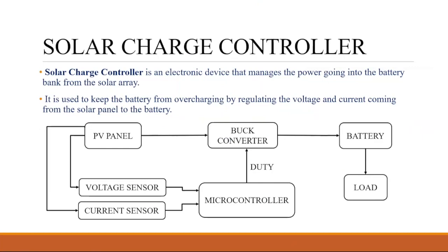Okay. And at the same time, if I directly connect the battery to the panel, what is the problem? There is a panel and a battery directly interconnected. There will be a problem of overcharging because there is no circuit there to protect it, right? And what is the problem with overcharging? Have you ever noticed that when you charge your cell phone and touch the back after 100% charge, it's a little warm? Because there's a chemical reaction in the batteries. Imagine you overcharge your battery. What happens? Its life will degrade, right? And the battery system is very expensive. We all know that. That is why comes the role of an engineer to design this charge controller system.